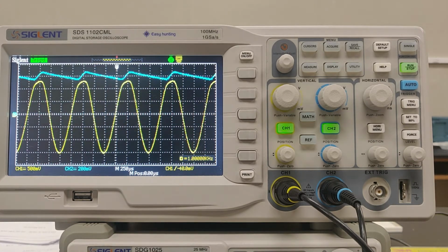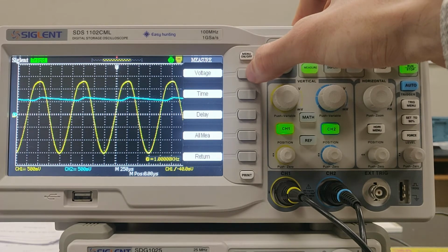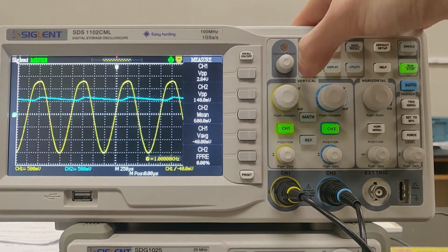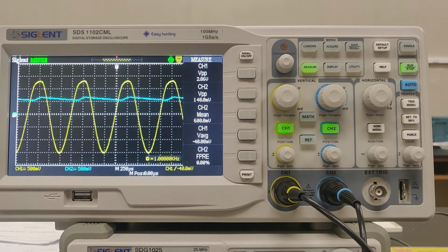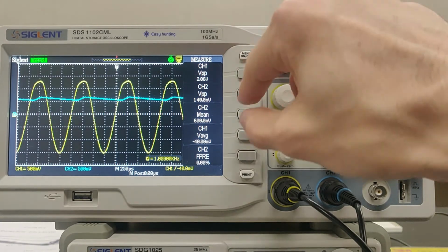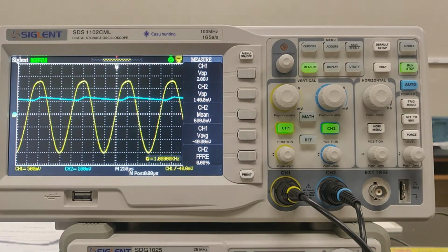So there. And now, with the larger resistor, our AC signal has effectively been turned into a DC signal. So much so that if I were to measure the mean voltage of channel 2, we do get an average voltage rather than an alternating, peak-to-peak signal. Even though our peak-to-peak voltage is really tiny, like 144 millivolts, our mean voltage, which is essentially our DC signal, is now 600 millivolts.